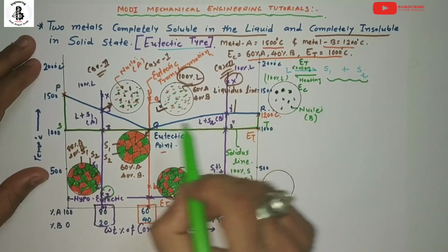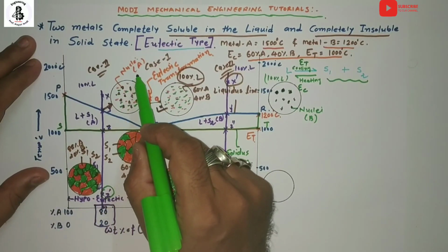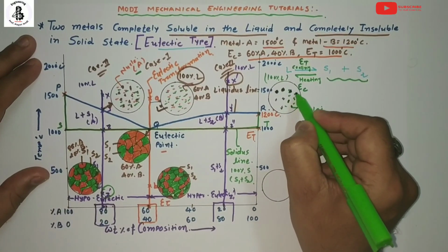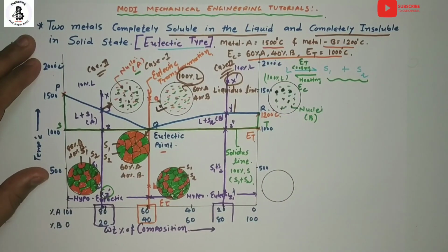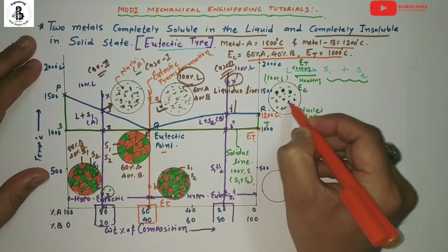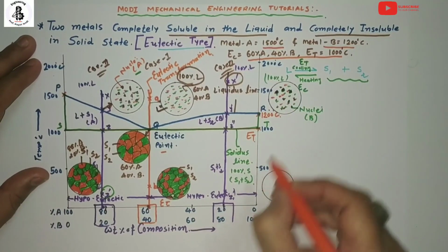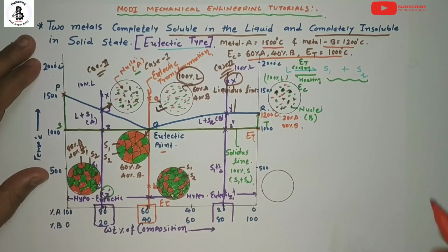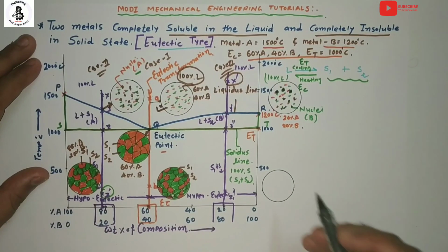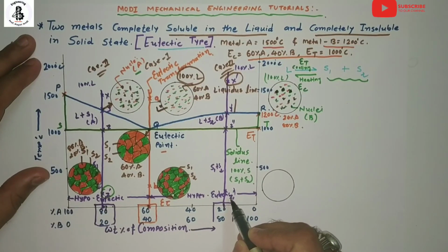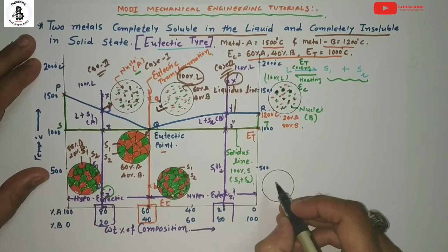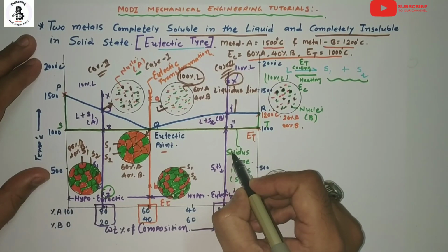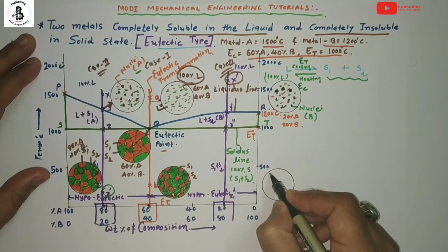In the previous case, just memorize, the nuclei were from metal A, and for the hyper-eutectic they will be from B, and the rest will be liquid for B as well as for metal A, with a composition around 20% of A and 80% of B. Now I would like to draw a microstructure at the Z1 dash point, around room temperature. That will make finer particles, because below the eutectic temperature line any composition forms two different solids. Just you can see.